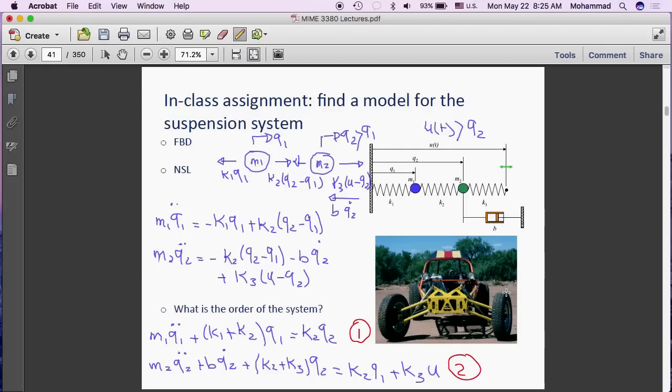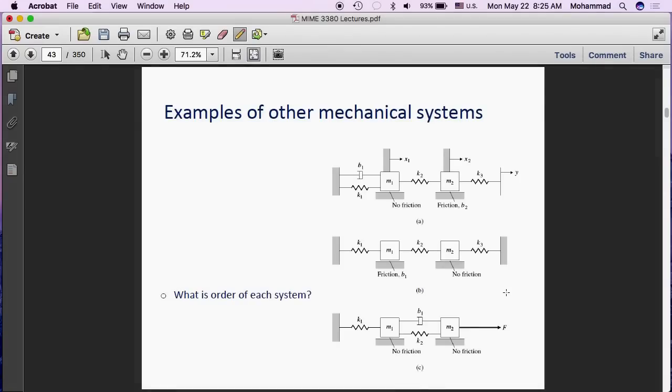And that's exactly the same approach we took with the first order differential equations. Didn't we do that? We said if you have a first order differential equation and you bring all the variables with x and x dot to one side, and you make the coefficient of x go to 1, the coefficient of x dot is going to be your time constant. As soon as you have the differential equation, you have some information about the speed of the system. So that's the approach we are trying to take here as well.